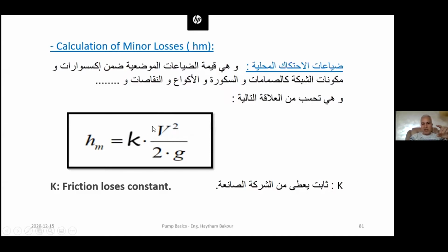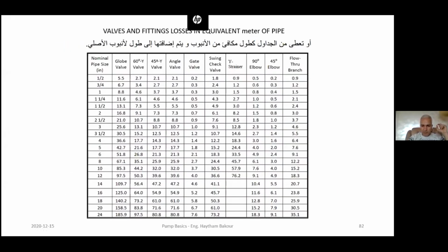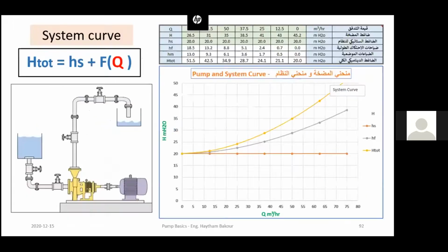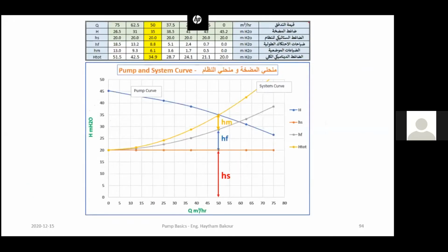And the speed is the flow rate divided by the surface area. So the losses are related to the square of the flow rate. If we have more flow rate, the losses have increased more. If the speed is doubled, the losses are quadrupled. As I said, some colleagues who are newly graduated maybe have this question. This is only clarification. Thank you.